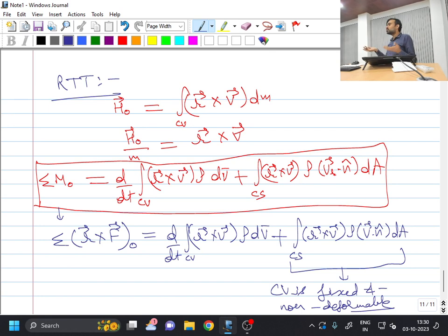Similarly, at our home we use the centrifugal pump for the majority of water pumping applications. Say you know the velocity at which water is approaching the impeller of a pump, and the velocity at which water is going out of the impeller of the pump, and you have to determine how much torque has to be applied on the pump to keep it rotating, so that water enters and leaves at the desired conditions. Then you have to do a certain mathematical analysis, and of course mathematics is the language of physics. This physical phenomenon can be mathematically represented by this angular momentum equation, and you can apply it to solve that particular problem.